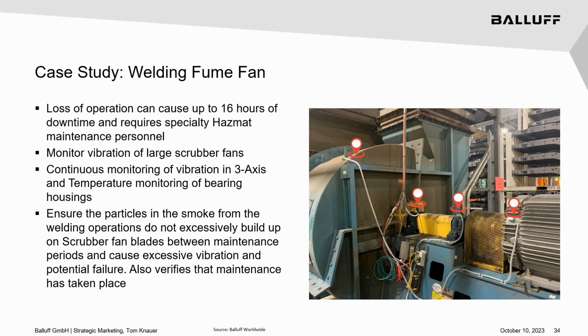They're able to, again, during a normal maintenance cycle, go in, clean that fan, and then restart the process without having to worry about a catastrophic failure. And in this case, because it's a welding fume fan, the whole operation has to stop if the fan fails catastrophically. And there's a long lead time to get the parts, long lead time to replace everything. So they're really saving themselves a lot of time and effort by being able to do the maintenance and the cleaning on the fan, which is a small cost compared to replacing the bearings and the motor and the fan itself in terms of a catastrophic failure.